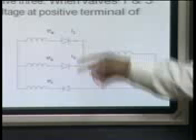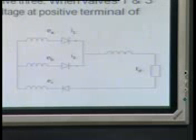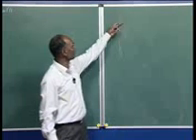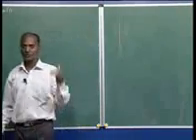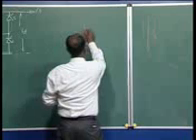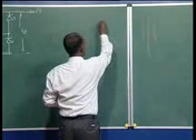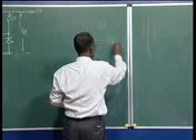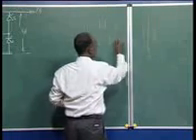So, in this case, as I said, the conduction pattern here is 1 and 2, then 1, 2 and 3, because here 3 got the pulse, and now the commutation between 1 and 3 is taking place, means the current I1 was your ID and I2 was your minus ID during this period.